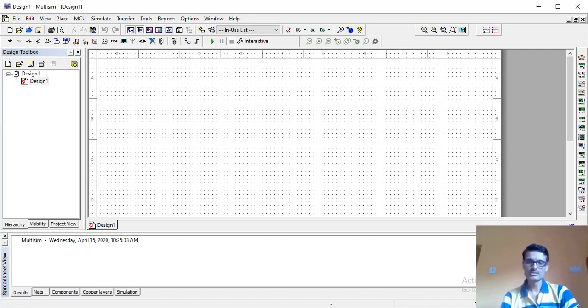Hello everyone. So in this video, I am going to explain the design and implementation of precision half-wave rectifier as well as full-wave rectifier. Now, precision half-wave rectifier is a circuit which is used to rectify, that is, to convert AC into DC, even for smaller voltages, like say even millivolt signal, microvolt signal can be rectified here, which is not possible by using a simple diode.